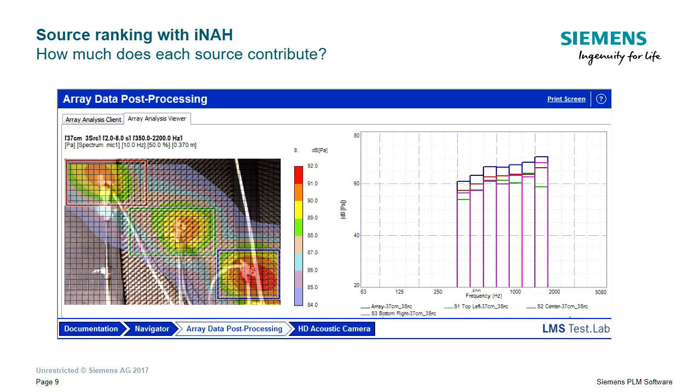We can actually prove that if we are close enough to these sources, we can be within 1.5 dB of the true sound power that you measure with ISO sound power techniques, which is within one of the engineering precision grade criteria that are defined in such ISO standards. So it can give you a very good estimate of the sound power.